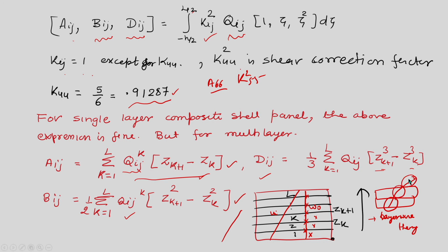So, the theory I have discussed here is valid for a thick shell theory, but it may not give very accurate results if you are interested in the interlaminar shear stresses. For that case, one should try either a 3-dimensional solution or the layer-wise theories.